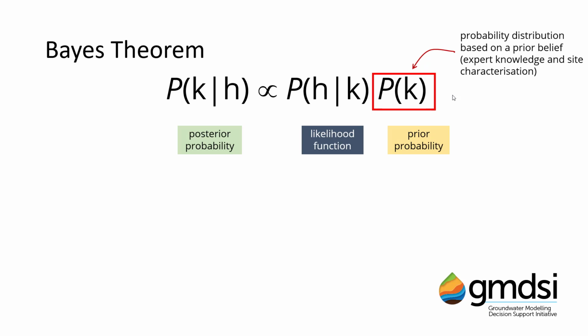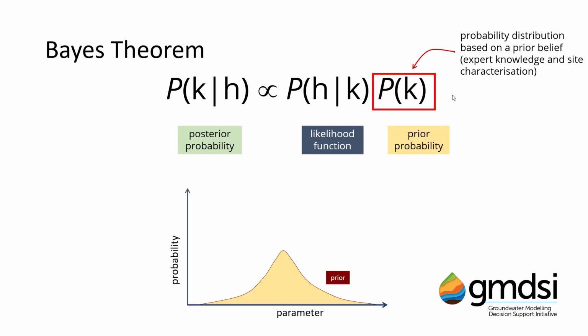We may have upper and lower bounds to describe what may not exist underground. We may even have some point measurements of some properties or have a variogram that describes how they are likely to be distributed in space or time. However, the range of what we don't know is usually pretty large. Nevertheless, we can still notionally characterize a parameter probability distribution based purely on our prior information. This prior parameter probability distribution represents all the possible values and combinations of parameter values which may exist at our site.